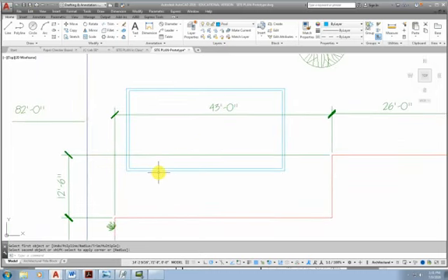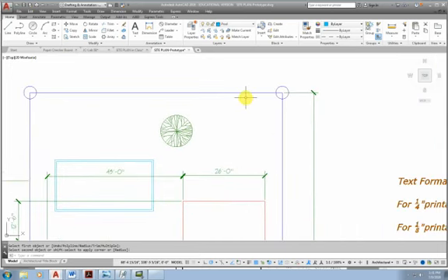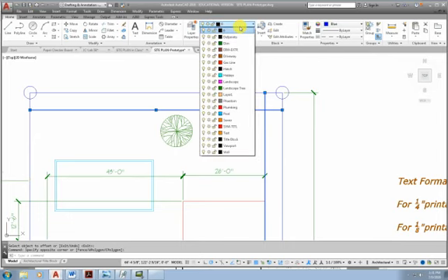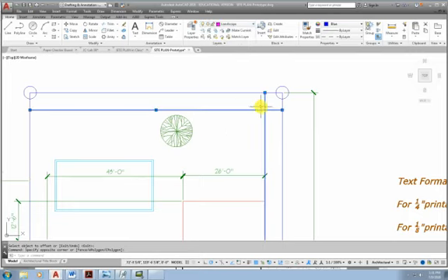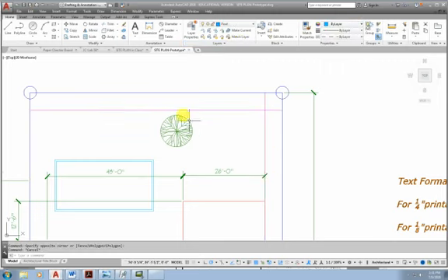So that's my pool, and then we're going to go and locate this flower box over here in the corner, and so we're going to offset that 5 feet 6 from the back two corners. So we'll say offset 5 feet 6. And then I'm going to just leave that, well, let's see what our options are for different layers. Not too many options, and so I'll just put that on the landscape layer. And I'm going to say by layer to get rid of any overrides. Fillet that.